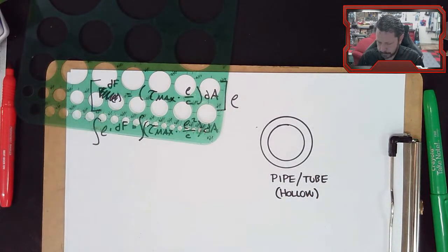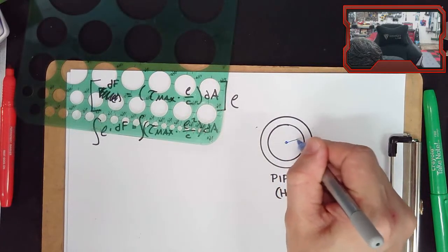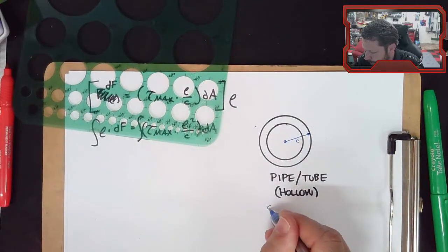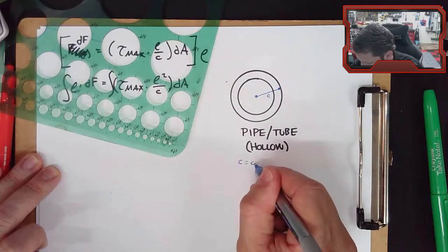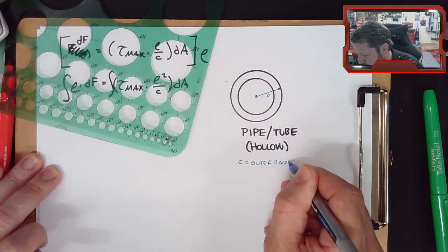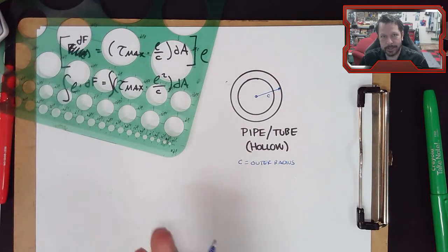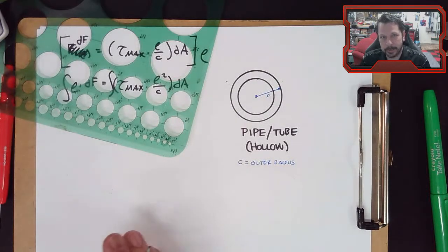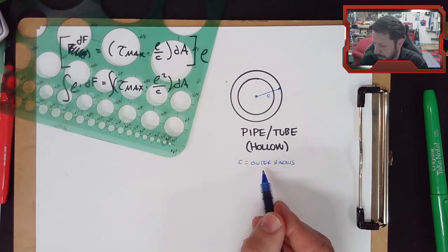And we've already established one of our variables is C. So C is the outer radius. You have to be careful with this, because a lot of times when you're given a problem to solve, you're told shaft information in terms of diameters, because you don't normally buy a shaft based on its radius, but based on its diameter. But the equation is looking for radius.